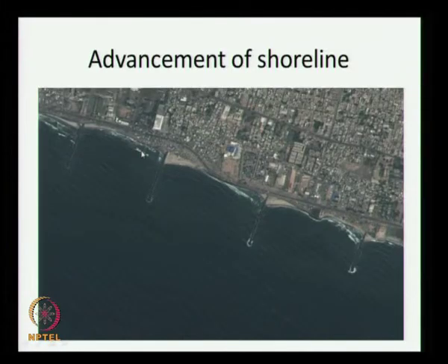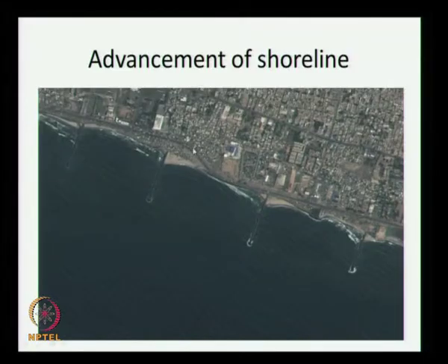Which is the northern side for this breakwater, for the groin? This is the northern side, this is the southern side. It is very strange that here on the northern side we have the deposition for this groin, and on the southern side we have the deposition for this groin. Depends on the season, which season you are taking the photograph. If you are doing it in the northeast monsoon, your deposition will be on the northern side. If you are doing it in the southwest monsoon, your deposition on the southern side. How much it has deposited, how much it is eroded, based on that your final shoreline will be seen.